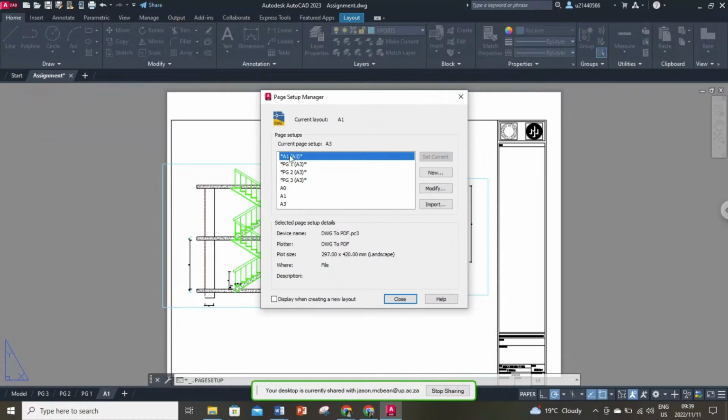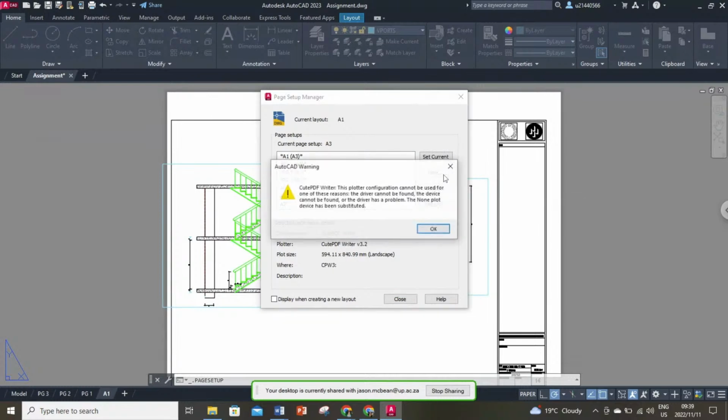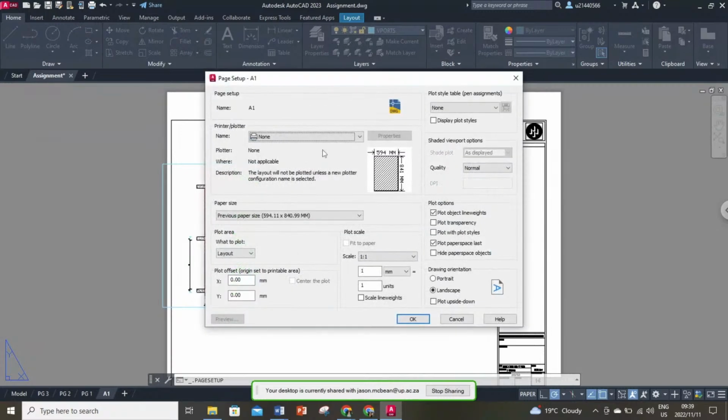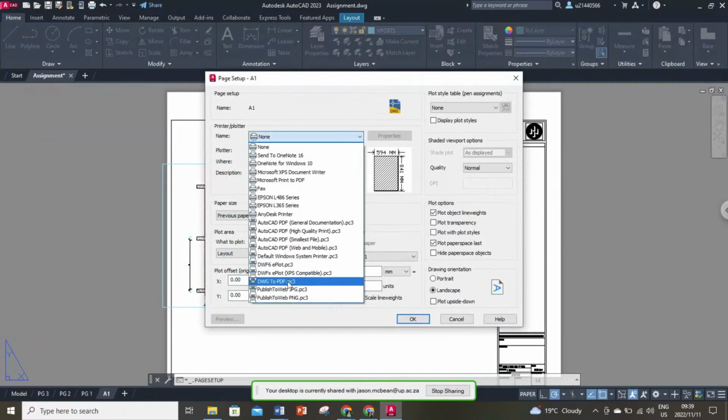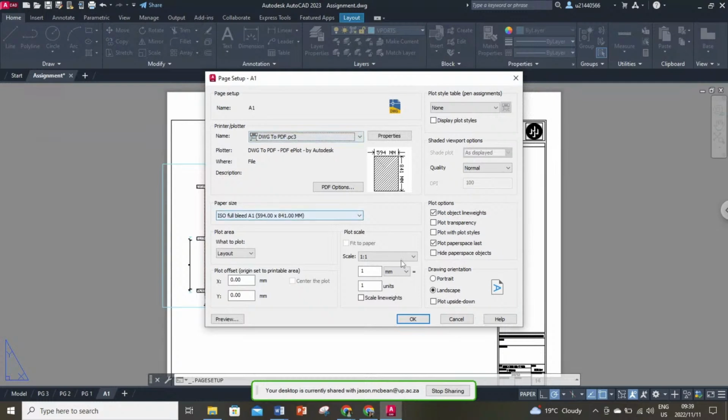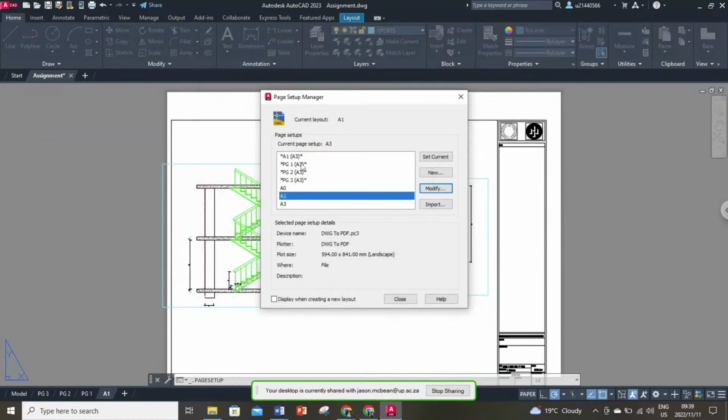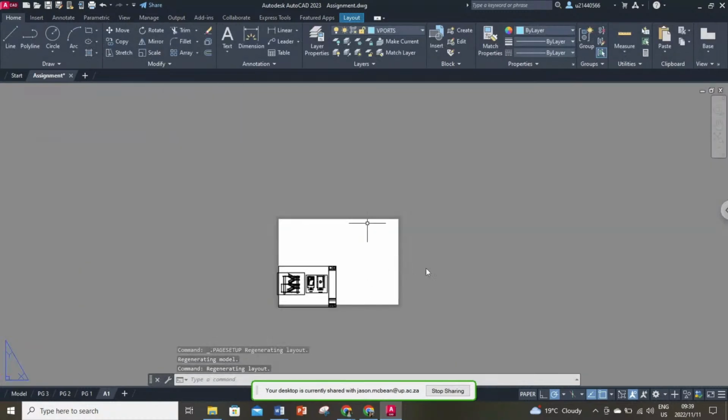Now, whichever of these views you're in, if you assign A3 and double click, say A1, you can see this is layout A1, but it's assigned my print settings A3. A1 will work the same, just maybe for the exam. Let me explain this. We can quickly modify this one, and we can set it up going forward. If you just keep these settings just like this, things will work really well. And you're going to go to monochrome. Okay, everything else is set, and if I double click now on A1, you see it changes to A1. If I close, you'll see that that's an A1 sheet.